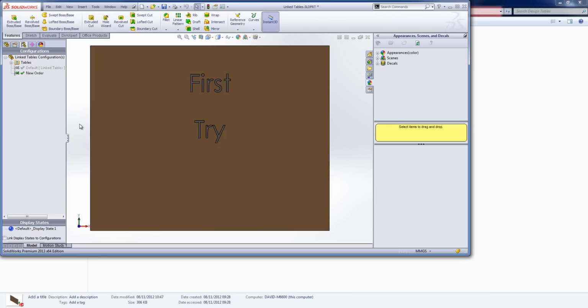So it becomes very easy for non-SolidWorks users to open their Excel file, fill the numbers in the columns that they understand, and then either yourself or if they have access to a computer with SolidWorks on, open up the SolidWorks file, watch it rebuild and get all of those new configurations in, and then potentially open a drawing and print it. They don't need to understand how the part was actually created or the design process behind the part. It's just allow the design table to do the updating. It's a really handy tool, particularly if you want to send details to customers, etc.